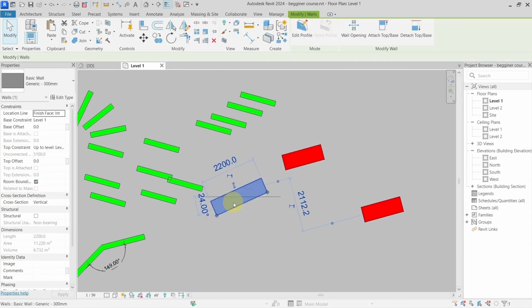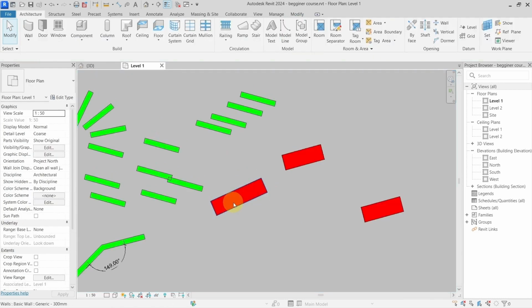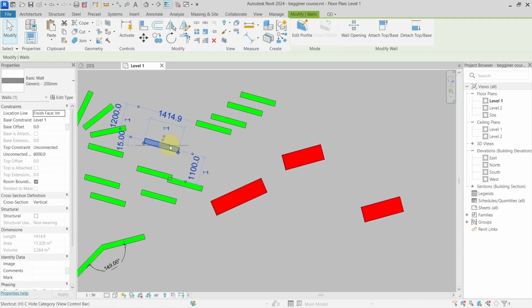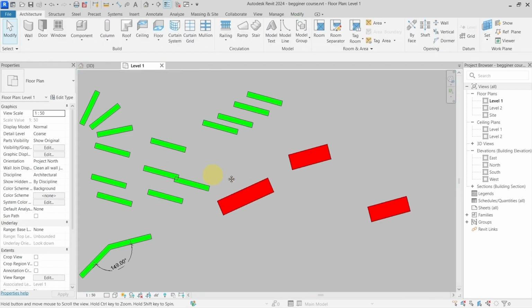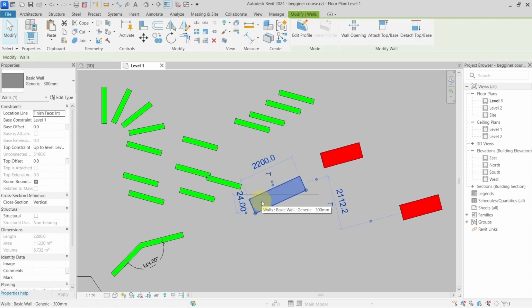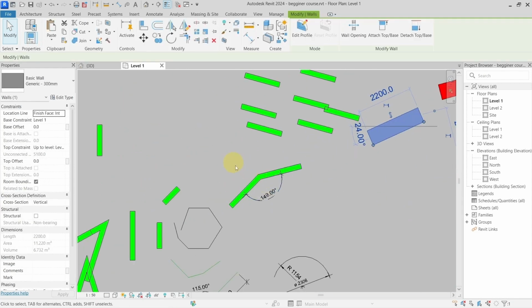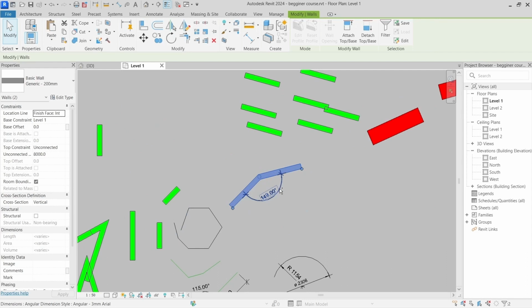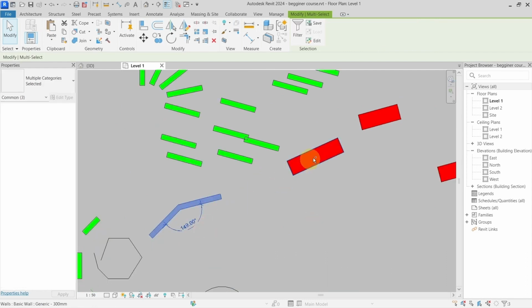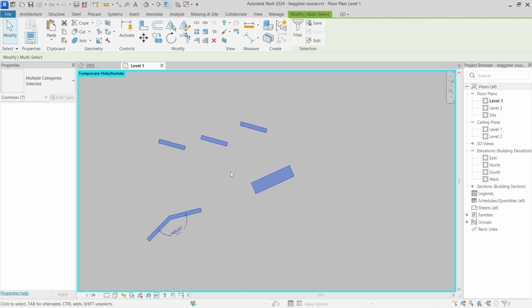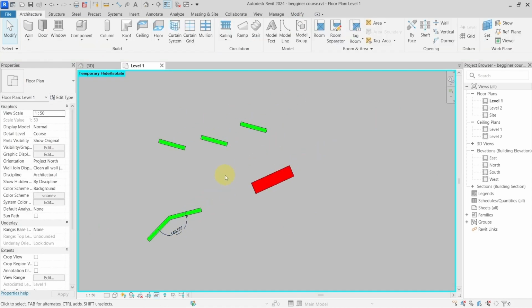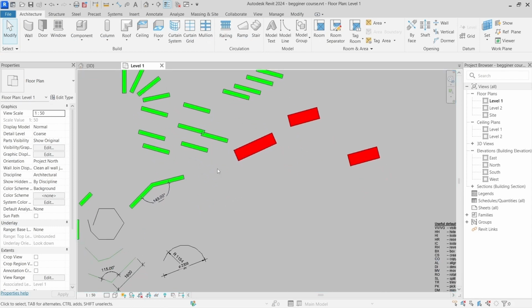So HI, HR, again HI, HR. It works not only for one element. Let's say that I want to now isolate only these things, so I can go only with my selection, press the HI, and it will isolate the things in my selection. HR, back again.